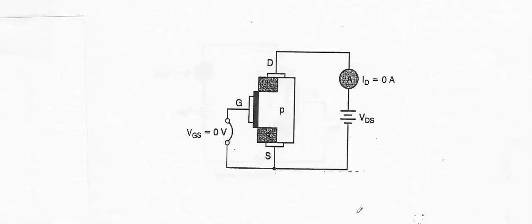And just to recap, if we go all the way back to a JFET, that's not what we have pictured here. I'll get to this. This is our E-MOSFET. But think back to the JFET, 0 volts at the gate. And for the JFET, the channel is as on as it can be. IDSS, and you can only deplete from that point. So JFETs are depletion-only devices.